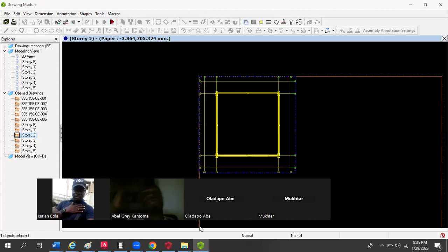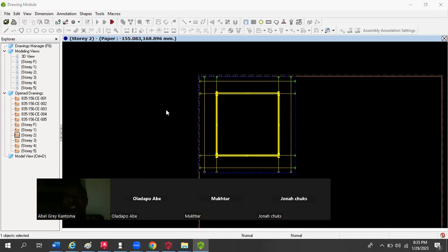Okay, I'm going to tell you. When it comes to steel design, what you need to print is all the structural members that you have designed. For example, for this overhead tank that we just designed, it has a column, 1. It has a reinforced concrete column that is carrying the steel, which is 2. And then that stanchion on top of that reinforced concrete is connected by a base plate. That is 3. Then it has an anchor bolt. Now, everything that has to do with that steel, you have to generate. So there is an anchor bolt, there is a base plate, there is a reinforced concrete column.